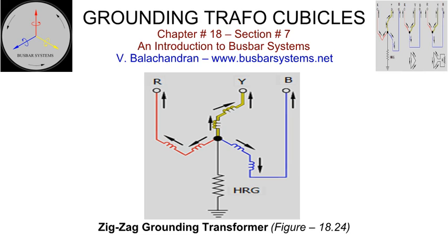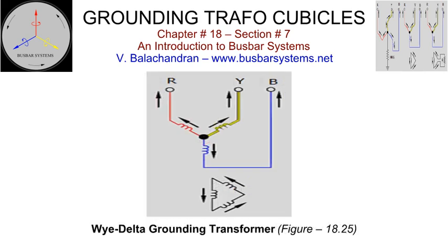As mentioned earlier, any equipment that is connected to the 3 phases of an isolated phase bus must ensure a reliable connection with the negligible probability of a phase-to-phase fault. It is therefore suited to be installed for smaller unit ratings connected to a 3-phase generator circuit breaker. Y-delta grounding transformer. Single-phase transformers with shell-type construction can be installed in individual compartments of the surge protection voltage transformer cubicle when separately installed. The line terminal of the primary winding is connected to the tap-off bus and the neutral terminal is connected to the earth in each of the cubicle.